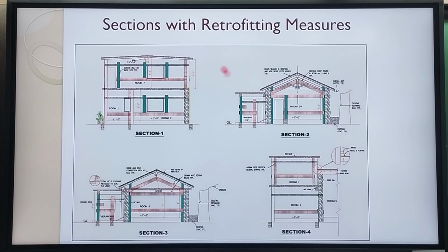This is where the old building is. Now this is the old building right here. So this had gable. The gable bands were not there. So you require gable belt, you require lintel belt, you require sill belt, and then you require also the vertical reinforcement in the corners, vertical reinforcement around the door opening, and also around the window opening.